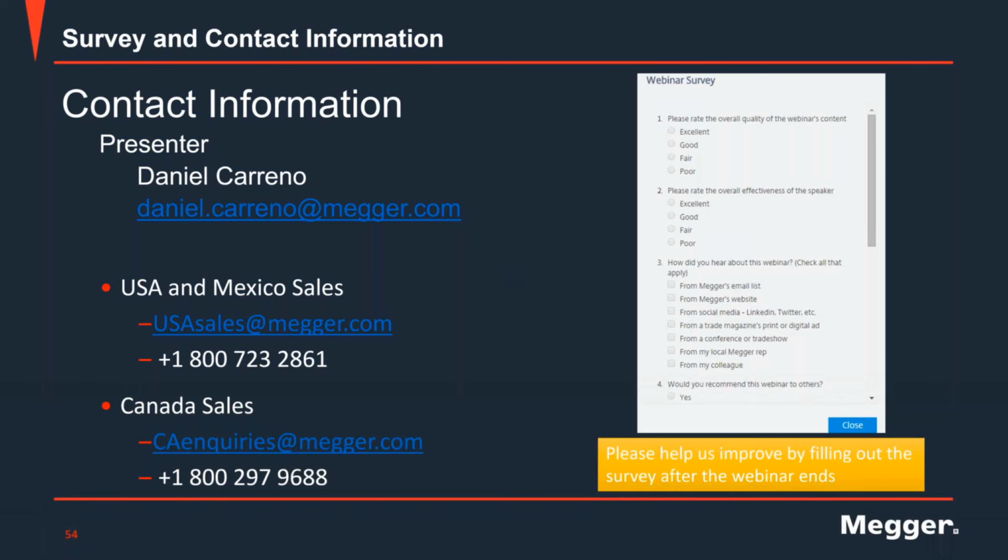Besides that, if you did the testing in the right manner and the value is still high, then there's something wrong with the transformer, and it needs to be investigated. It may be that the transformer is designed in that manner, but again, like I said, the standard says that 0.5% is the limit for transformers.